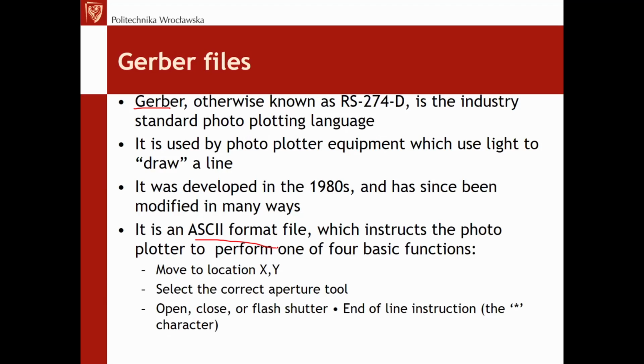In the case of Altium Designer, there are Gerber files for each layer, as mentioned. So we have a separate Gerber file for the top layer, a separate one for the bottom layer, for the middle layer, and separate files for the top overlay, bottom overlay, solder mask layer, also for mechanical layers and for keep out.